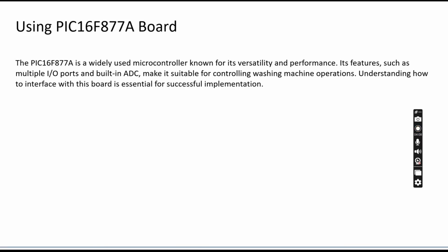and then drains the water for 3 seconds. In Proteus, we can simulate the setup by connecting virtual components, testing the logic without hardware. Then once verified, we use a programmer like PICkit to upload the code to the PIC16F877. This approach ensures reliability before building the physical system.